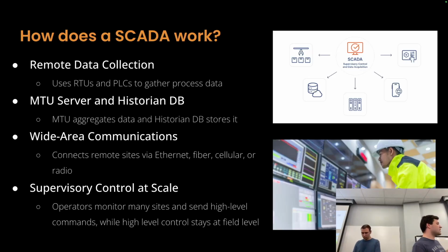What I really mean by that is the operators are able to give a high-level command, like let's open breaker 12, and the PLC will actually execute that logic and make sure that the high-level command is then executed safely at the lower level. So it just gives off a high-level command, and doesn't have to deal with the actual logic and whatnot that a PLC deals with.